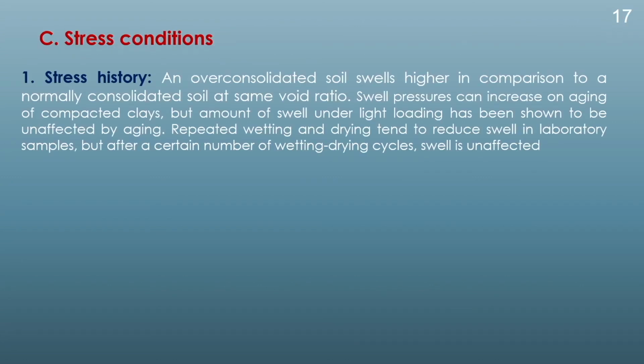Now next comes the third condition, that is the stress condition. In the stress condition, the first one is the stress history. An over-consolidated soil swells to a higher value in comparison to a normally consolidated soil at the same void ratio. The swell pressure can increase on aging on compacted clays, but the amount of swell under light loading has been shown to be unaffected by aging.